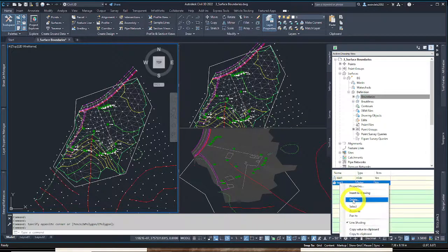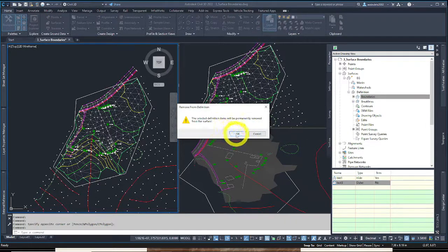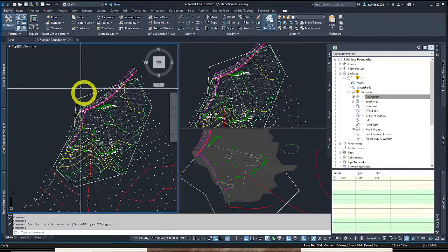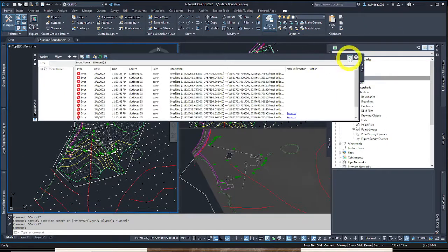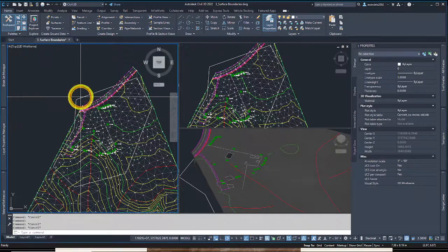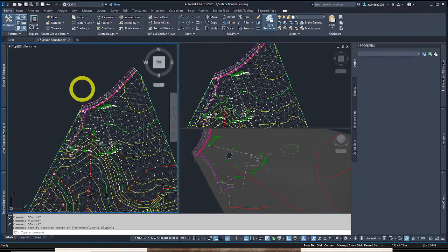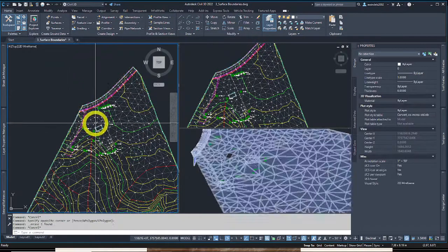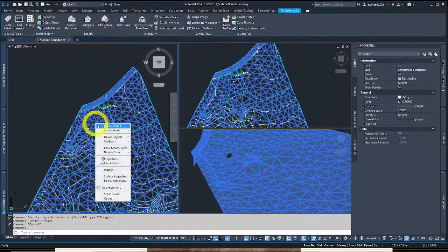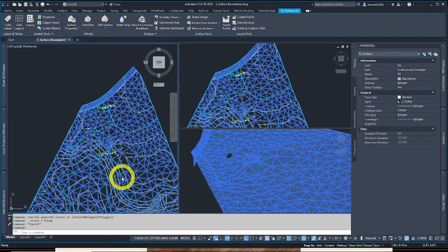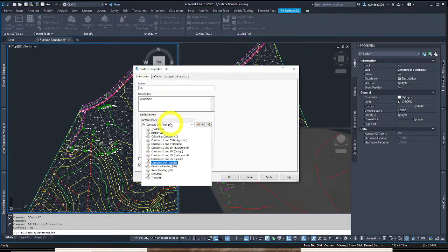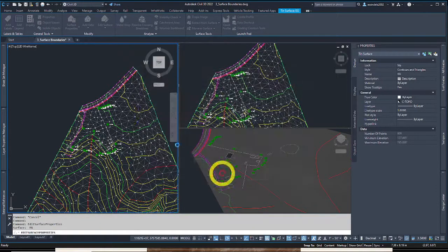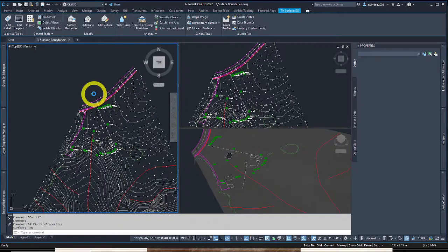Let's remove that and get back to the task at hand. Rebuild. I said ignore these errors most of the time if you have to go back and forth, especially undos and redos. Be very careful with major Civil 3D operations on some of these undoing and redoing. Do saves many times before you do undos. It's a very notorious area of crashing, and Civil 3D will hit that. We'll go back to where we started.